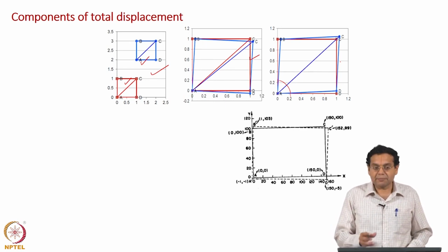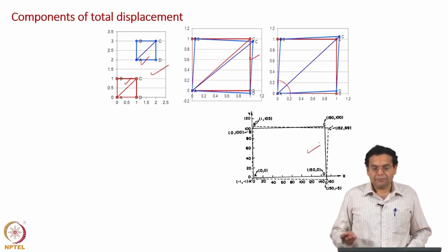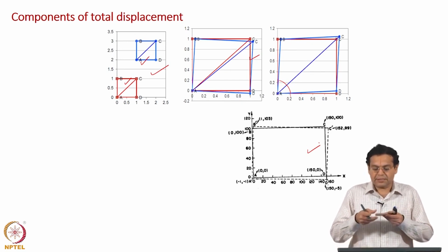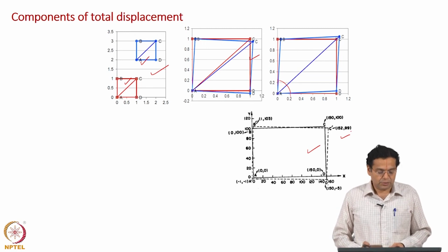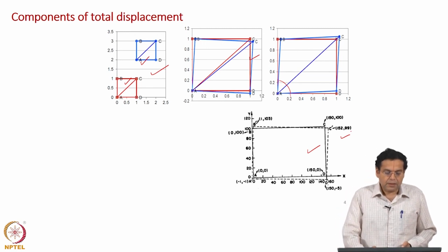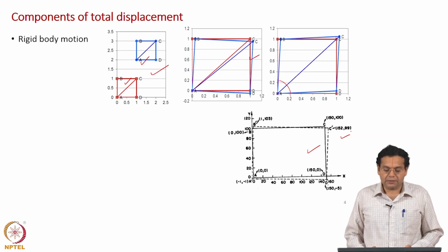Of course we have not discussed normal strain here. This particular example did not have normal strain, but we took another example where we had normal strain, shear strain and rotation as well. Of course, this example does not have translation, but here also we concluded that when there is normal strain, change in the length of the plate, let us say, then there is change in coordinate or displacement. So, now if you want to put them all together, what are the components of total displacement?